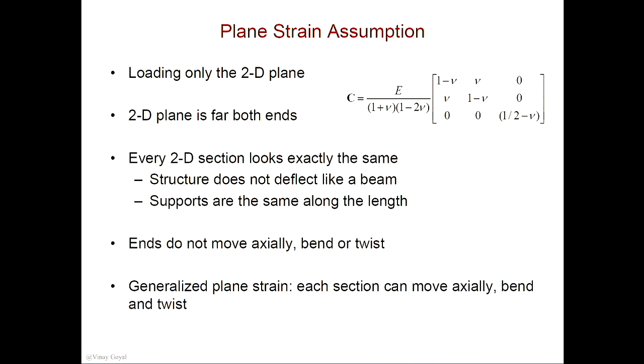An example is, take a pressure vessel and say the pressure vessel is about 20 feet long. I'm just making an example. Then I can take that cross section and just model that, because it's so long that if I'm looking at stresses in that plane, you could basically assume they're the same all the way through.